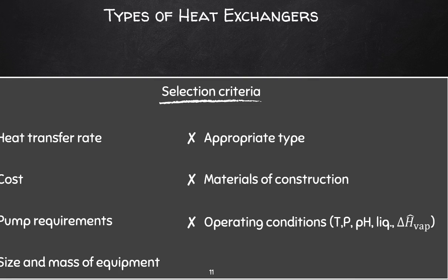Also consider the cost and benefits, as well as the operating conditions, the temperatures and the pressures. If high pressures and temperatures are expected, or fluids will undergo a phase change, then a shell and tube heat exchanger would probably be the preferable choice over a plate and frame heat exchanger, for example.